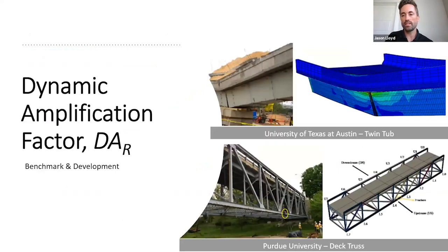Next was the characterization of the loading conditions in a steel bridge after the failure of a tension member. A sudden failure, for example, brittle fracture, of a primary steel tension member is a high-rate dynamic event, and the post-fracture deflection is also a dynamic structural response event. The inertia of the deflecting bridge will amplify the static forces present in the post-fracture structure under static load conditions.